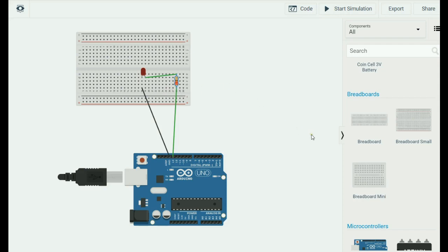So you would have to either put the resistor like this, from here to there, so that the two leads are on different channels, or you can do what I did before and just place it like this, because this channel and this channel down here, they're not connected. All right, so enough with that.